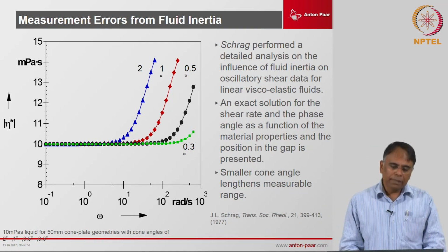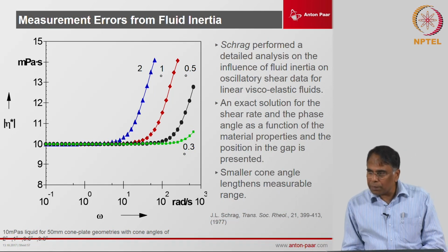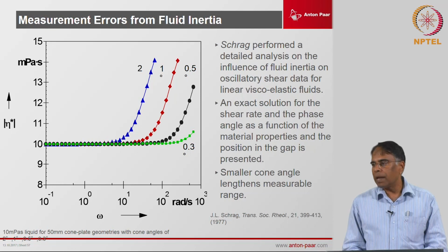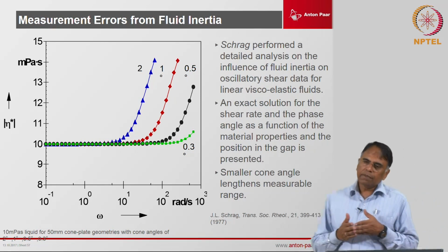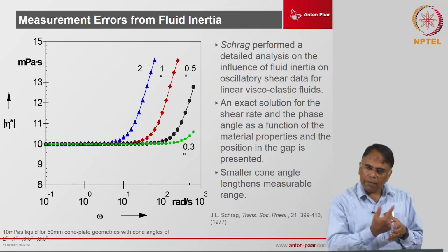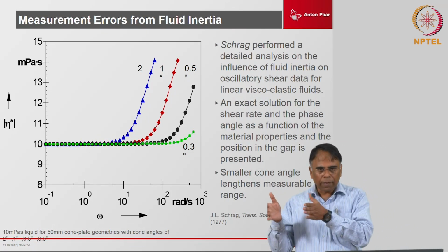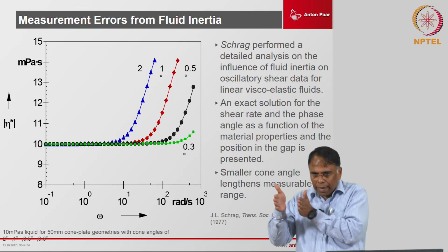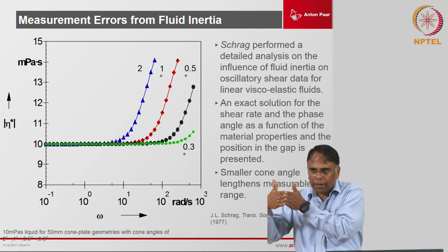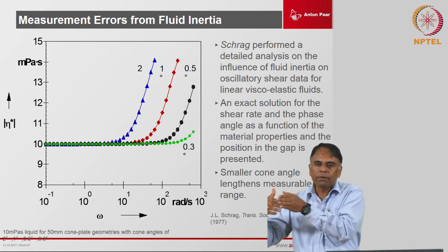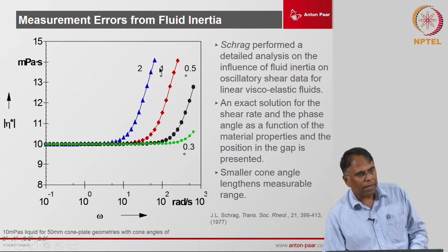At high shear, this is one of the things that can happen, specifically if you are measuring very low viscosity materials at high shear: you get what we call the secondary shear effect. The secondary shear effect is nothing but the material, which was having a laminar flow, going into a turbulent flow. When it goes into a turbulent flow, the layers which were flowing like nice laminar sheets are now crossing each other, and that is causing that extra shear, and that is why you can see the viscosity increasing as a function of time.